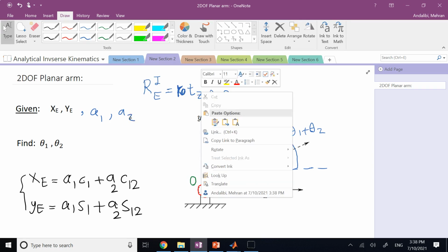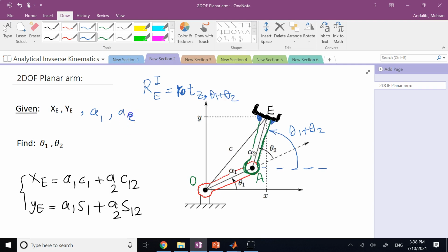So in this case, all you really need to care about is the position. Because again, the end effector is not separate. There is no joint between this end effector and the second link. So you need the first frame, you need the second frame at point A. At E, you really do not need an extra coordinate. Okay, so 2 equations and 2 unknowns, you clearly can see.